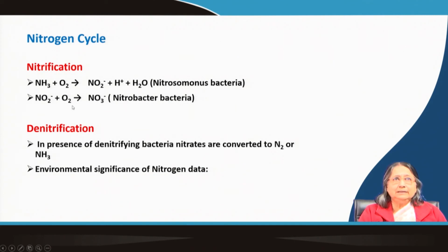So that means this oxygen, this is the dissolved oxygen that is present in water, okay. So it is giving the NBOD. So this is the thing that is happening and it is called nitrification. But what is denitrification? It is also done by some type of bacteria, the denitrifying bacteria, okay. What is happening? Due to this type of bacteria, nitrates are converted to nitrogen, or this is reduction.